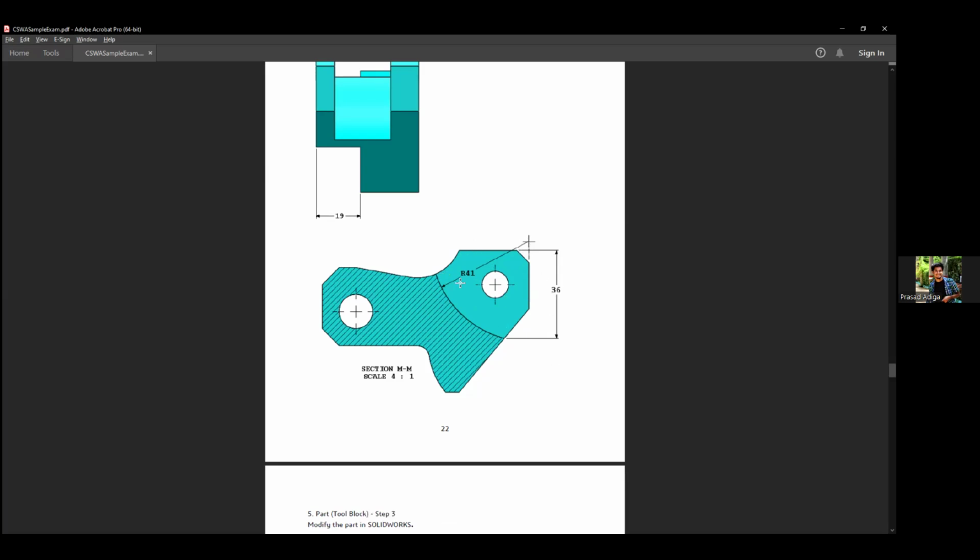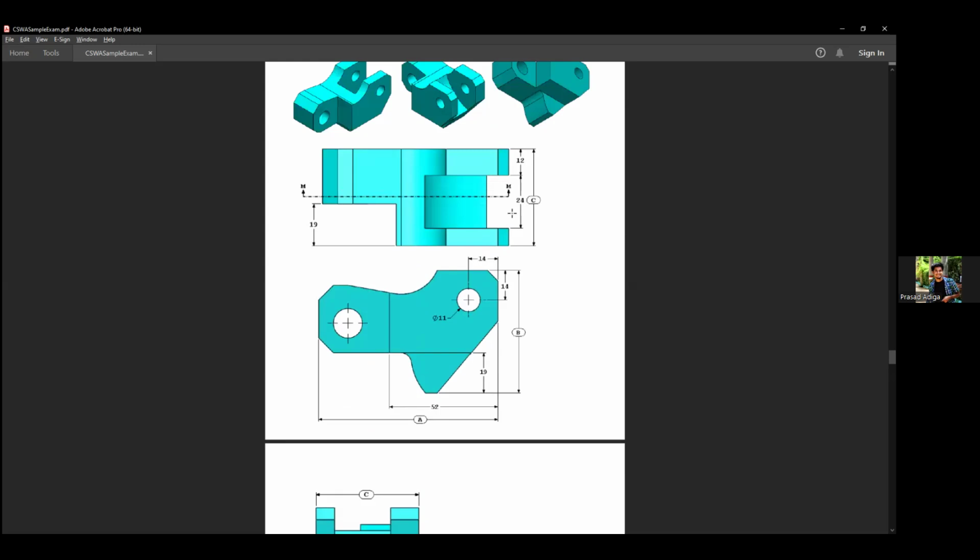So to make sure that you're getting the exact curve as the drawing, this center of curvature has to be horizontal to this edge. Let's do that. And before we do that, as you can see here, there is a 12 mm depth from the other side, and then they have given 24. So this remaining edge is C minus 24 minus 12, right?